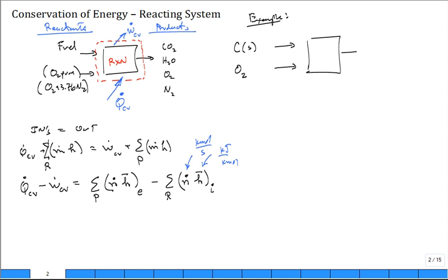What is the product going to come out? Am I going to get any water vapor? No. Let's say it's 100% theoretical oxygen. So there's no unused oxygen coming out, just the perfect amount. Let's write our balanced equation for that. So we'll have carbon, leave a 1 in front of it for the stoichiometric coefficient because it's our fuel. Leave a space for how much oxygen we need. Come over here, carbon dioxide.